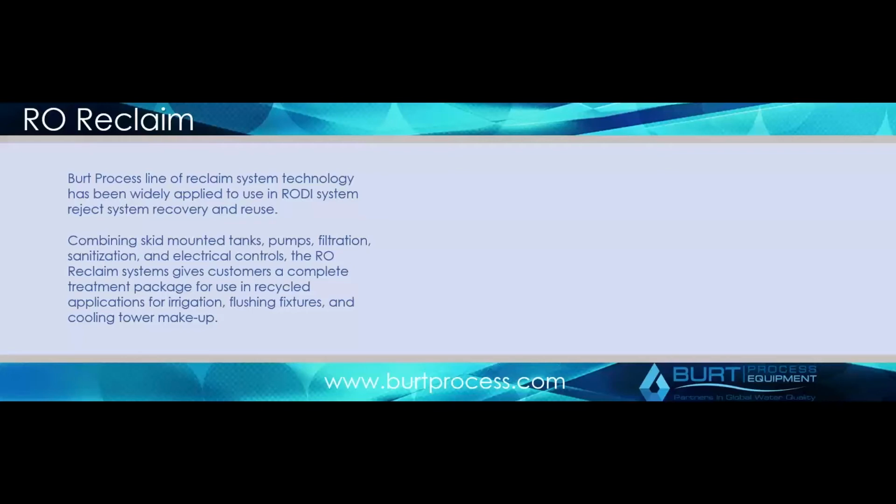Really what you're talking about when you have nitrogen blanketing is not a bacteria issue, it's to prevent the atmosphere from getting drawn into the tank. When you're generating water of a certain quality, literally the CO2 of the atmosphere can want to get dissolved back into your water, and that can basically allow the resistivity of your water to actually drop in those cases. So you're talking about very high purity, like ASTM 1 or above. You very often put a nitrogen blanketing system in there to allow that water quality to be maintained at all times, a very thin layer.